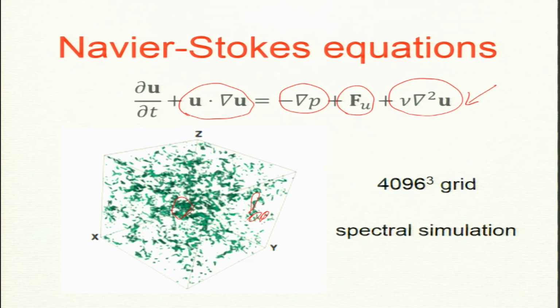This curl of u is not homogeneous. Normally we assume that density is homogeneous, but this is not homogeneous. So, it is a multi-scale problem, that is one important point, and we will discuss later that dissipation occurs at a smaller scale. Something happens at very small scales, small scales are important, and it is called a singular problem. Length going to 0 you need to consider properly. This viscous term plays a very important role, but some phenomena happen at large scale, some at small scale. So, there is a lot of interscale interaction.